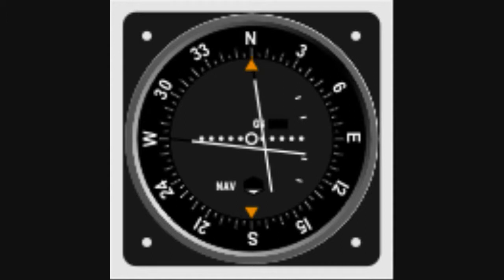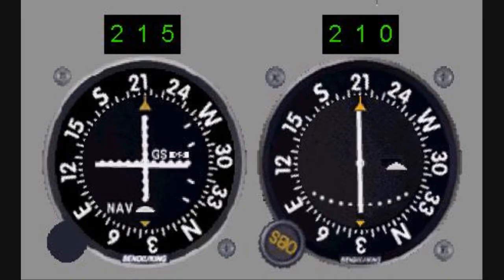Now, one of the best things about this gauge and the other VOR gauge, which I forgot to mention earlier, is that you can use the autopilot with them. That way you can stay on your VOR radio by just using the autopilot. It'll keep your horizontal navigation, it'll keep you right on the radio, and you won't have to stress out about keeping your airplane straight and correcting. You can worry about other more important things, such as fuel or navigation. The autopilot makes life easier for you if you make it easy for the autopilot.